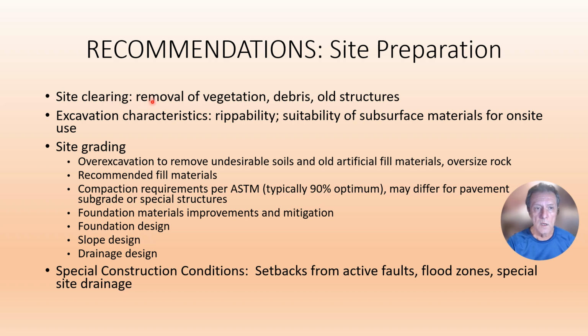What kind of site clearing do you need to do? Do you have to remove vegetation, trees, bushes, forests? Do you have debris that's been dumped on your site? Do you have old structures like old septic tanks or old homes or old buildings that need to be removed? You have to address excavation characteristics. If you're on a bedrock site, can that bedrock be removed or cut down by ripping into it with heavy equipment, or are you going to have to blast? Is it too hard to be ripped by dozers?